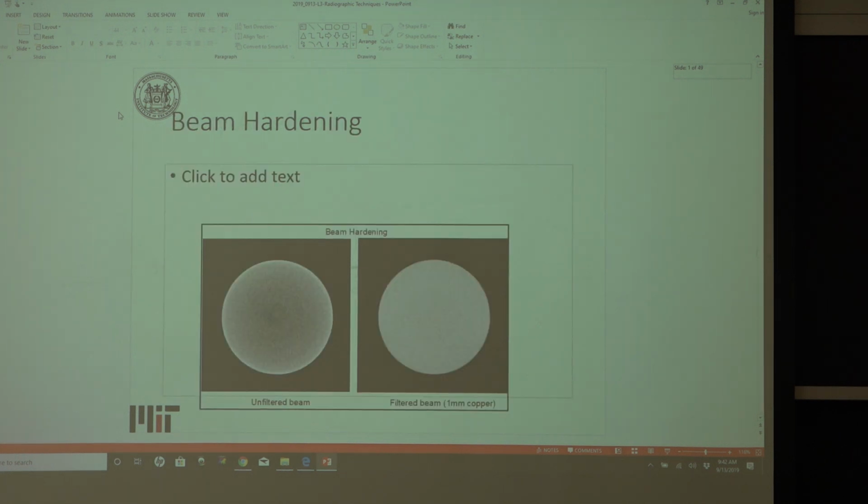And the last one is for beam hardening. If you know that your X-ray beam, you know a certain X-ray you have to use. The beam itself can lose focus if it has a geometry that is not something circular, so based on the geometry, you can get beam hardening. For beam hardening, this is where you can put different filters in to compensate.